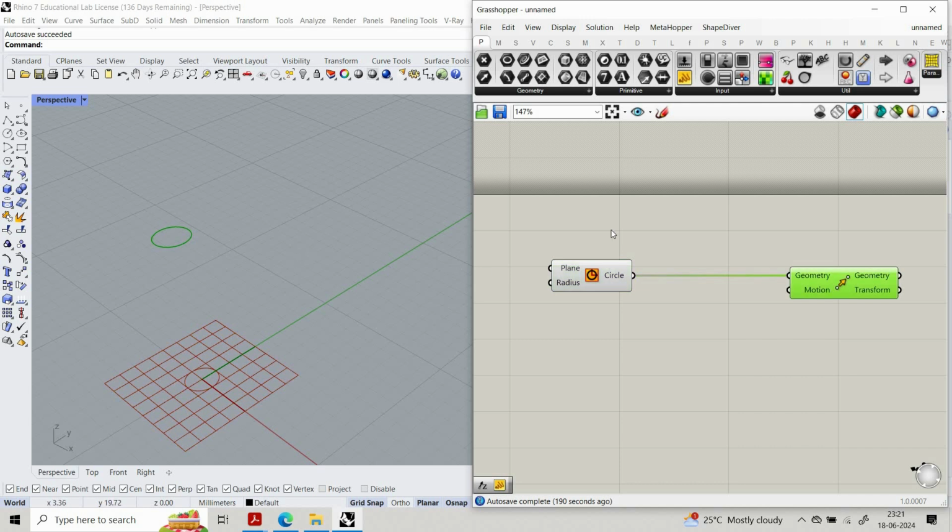The good thing in Grasshopper is that at some point you can use the input, that is the start of a geometry which is not changed. You get access to that geometry before edit, and this is after edit, so you get access to both geometries, which is so helpful.